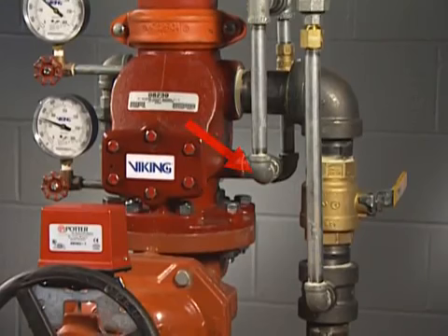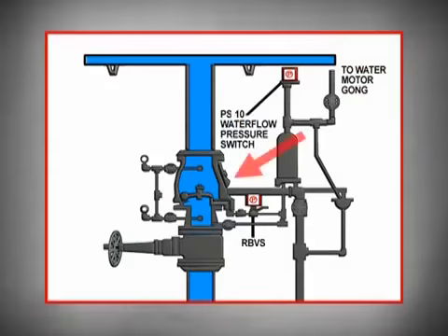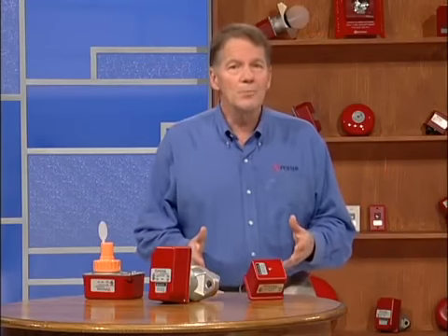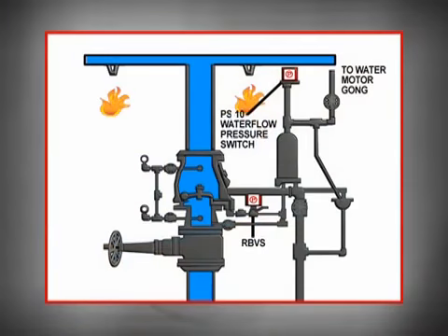Some of this water is diverted through piping called trim to activate the pressure-type water flow switch or ring a mechanical bell called a water motor gong. Under normal conditions, the alarm valve traps pressurized water above the clapper and prevents reverse flow from the sprinkler piping. An external or internal bypass reduces the possibility of false alarms under low flow conditions. When the water supply pressure exceeds the sprinkler system water pressure due to a sprinkler opening or a surge in the supply water pressure, the valve opens and the alarm port is exposed to incoming water.